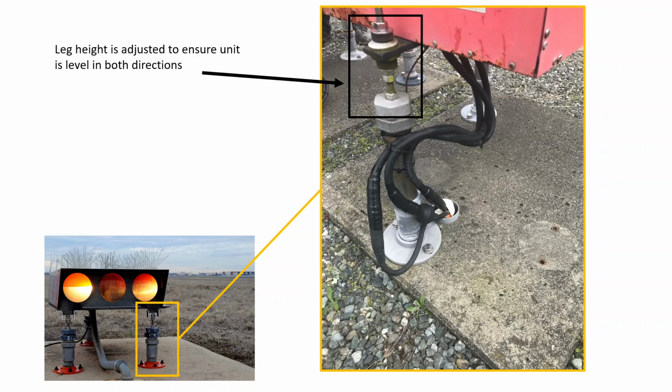And here's the leg height adjustment, ensuring that we only adjust 2 of the legs if there are 3 present. Never adjust all 3.